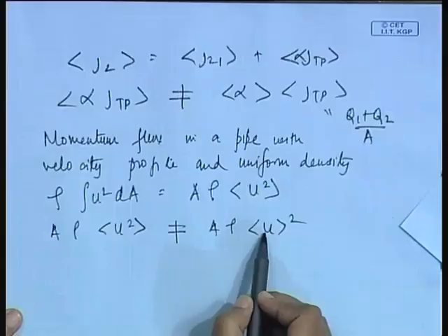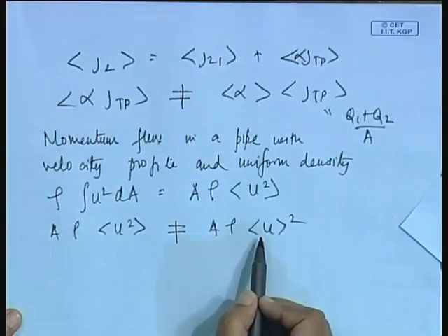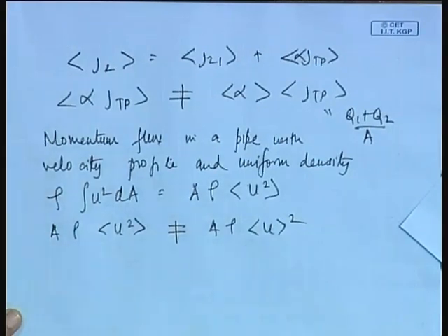So, in single phase flows, what did we do? We just took the ratio of these two and expressed it as a correction factor. If you remember, this was the exact thing which we had done in Bernoulli's equation. The basic equation is just u square by 2 plus z, delta p by rho plus delta u square by 2, and then we introduced a correction factor alpha there. The alpha was the kinetic energy correction factor.